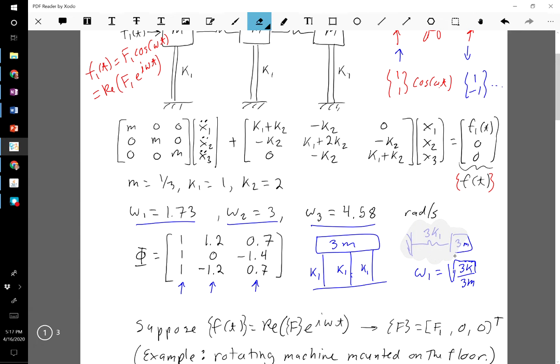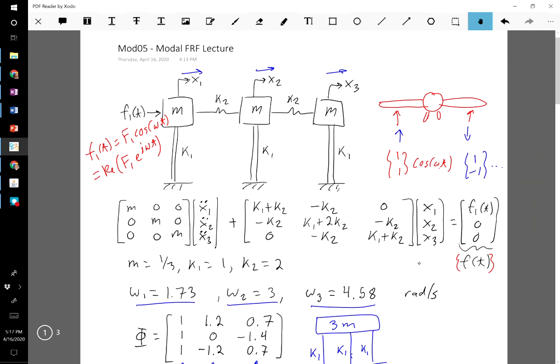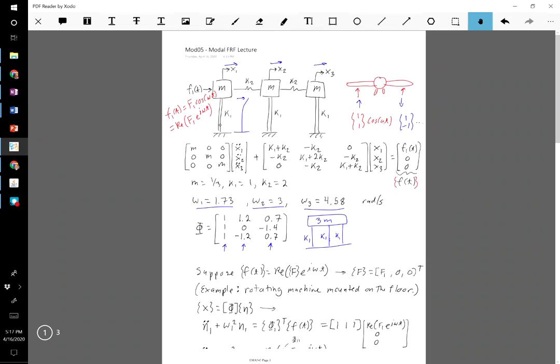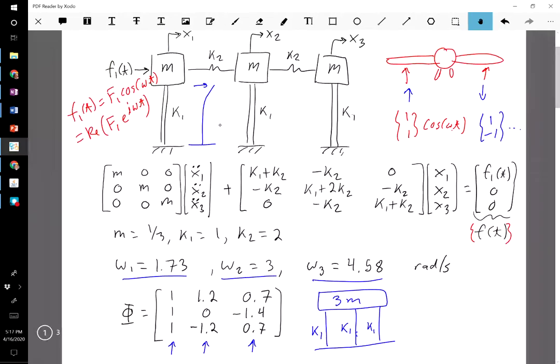Similarly, actually, I guess it's worth backing up and saying, I just took for granted that you would recognize that these 3 springs on the bottom, K1, are beams, right? So a beam, when we apply a load, can deflect kind of like this. And so we're saying that it can be represented as a spring with some equivalent stiffness.